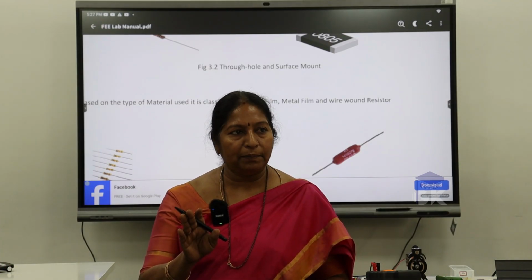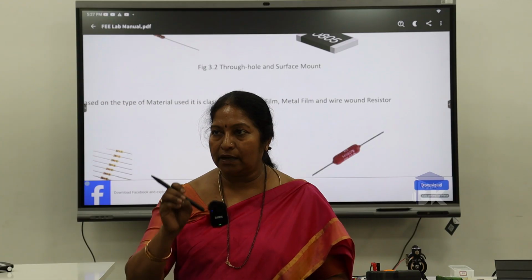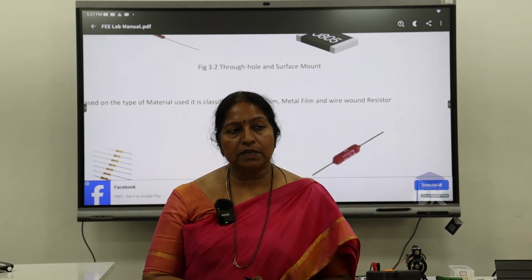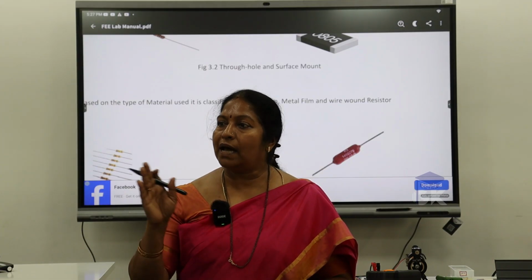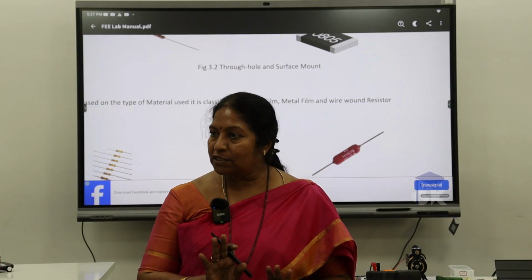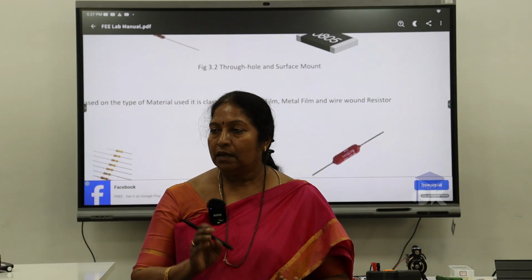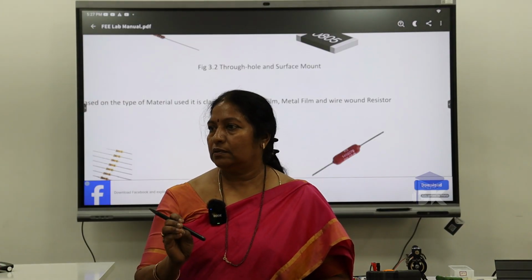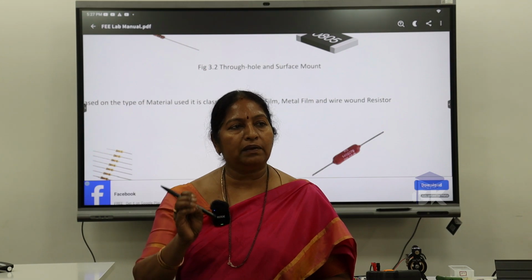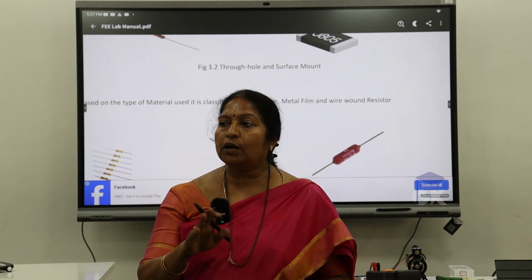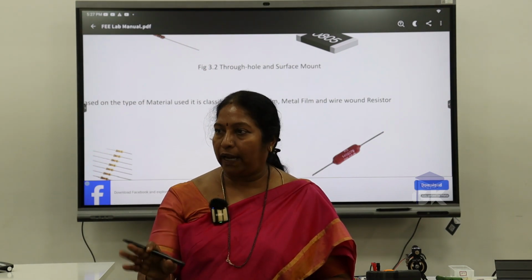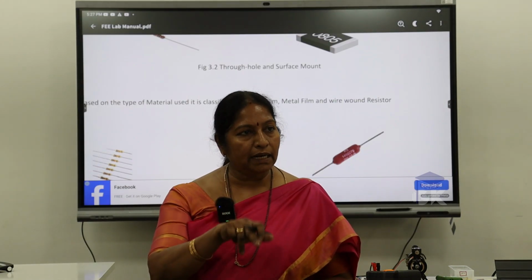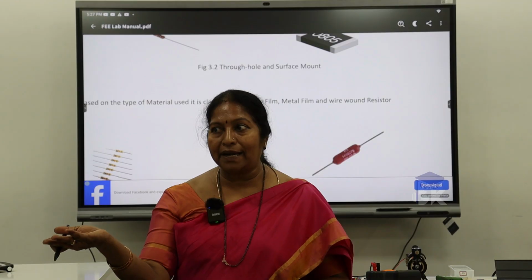Because in a circuit, let me say, I just wanted exactly 920 ohms. Because of this tolerance, if it goes to 1100 ohms, it's no use for me. Certain circuits which are very critical, there the resistance value should be exact. 1 or 2 ohms or 10 ohms tolerance is okay. 10% means for 1K it may be 900 ohms, it may be 1100 ohms.